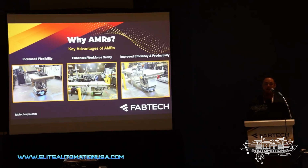So this customer had 2 injection molding machines right beside each other, 2 operators, long cycle time, 2 minutes roughly, but it just wasn't quite enough cycle time for one operator to walk from one press to another. So what we did is we took the AMR and we took that part, we transported it to press number 1. So the AMR took the part from press number 2, brought it to press number 1, and was able to consolidate that down from 2 to 1 employee.